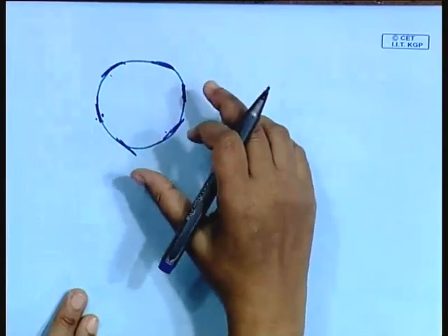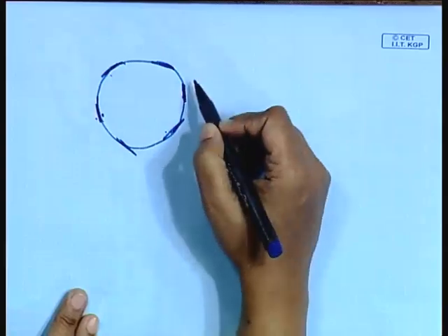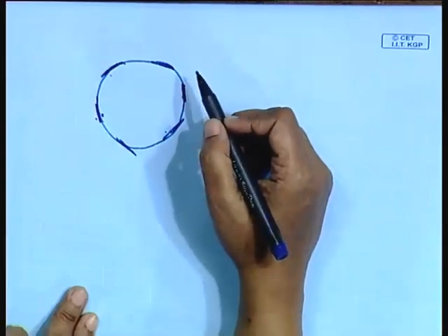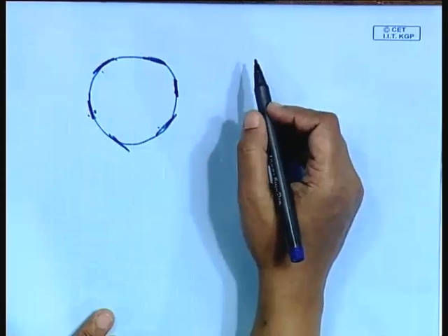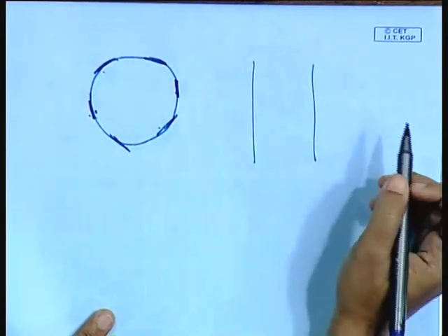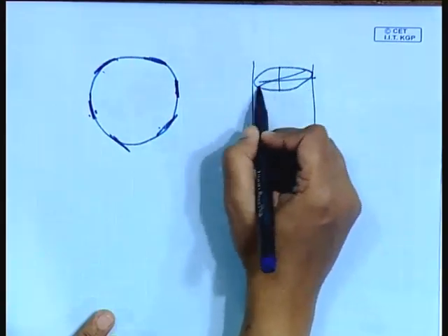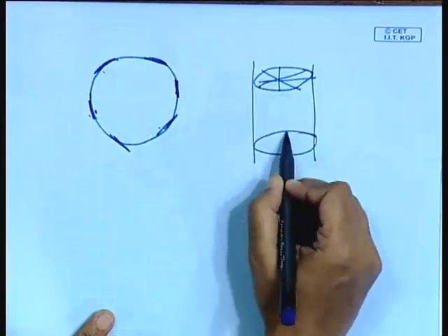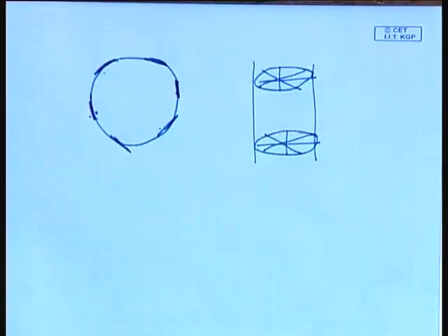So, what I want to emphasize to you is that depending upon the design of the probe, this particular technique can be used for a wide range of purposes. And suppose we want to measure the volume average, what will we do? We can have one wire mesh probe here, and one here, just like the strainer through which you strain tea.